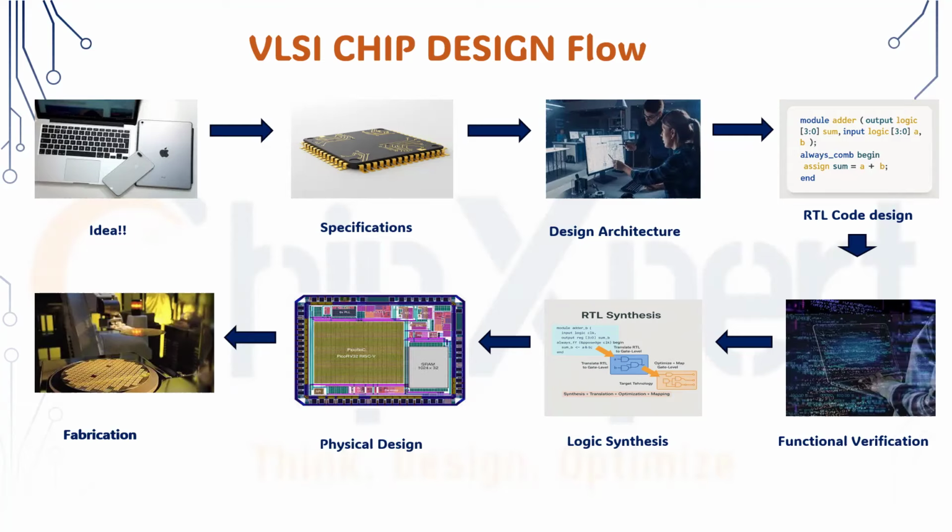Okay. Then the physical design team will deploy all this in a CMOS structure, or transistor level. Okay, this will be created. All these transistor levels are created by the analog layout tools. They will give each cell's characteristics. Basically, if you have an AND gate, that will be converted to CMOS level, which will be defined by the custom layout or analog layout teams.